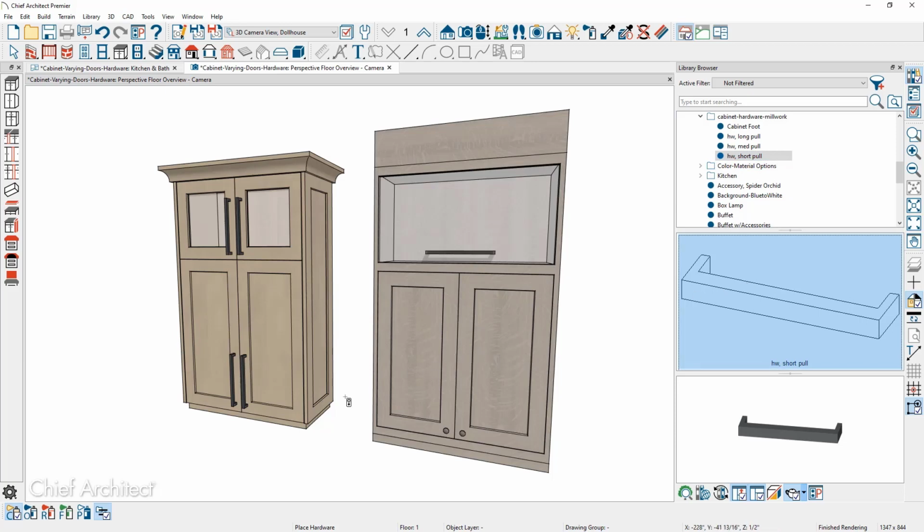In my lower left hand menu system is the scoping for the library object painter. Component mode, object mode, room mode, floor mode, plan mode. In component mode, I'll click on the face item. Notice how my cursor changes to a replacement icon. When I get that icon, that's when I'll click to apply that specific hardware item.